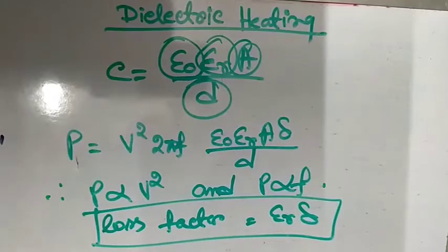Therefore, additional units of electrical capacitance or inductance must be used either in series or in parallel or in a combination of both with the workpiece in order to match the impedance of the load with that of the generator. In general, as mass of the workpiece increases, the optimum frequency decreases.